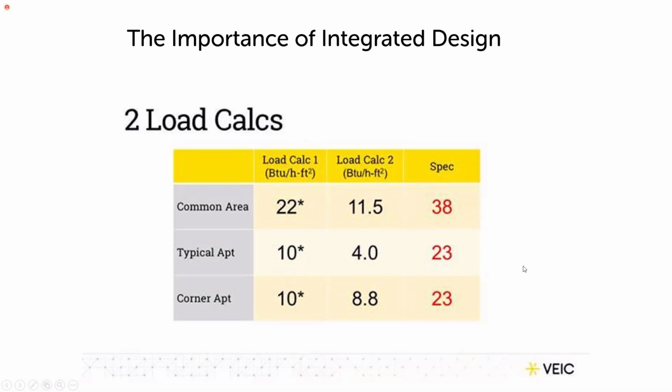So instead of having efficient heat pump equipment running, basically these units were being heated by electric resistance heat because the heat pump was coming on and off, on and off, on and off, and it never ran in a modulating fashion. So this is just an example from the field of what those implications can be for taking assumptions rather than careful load design.